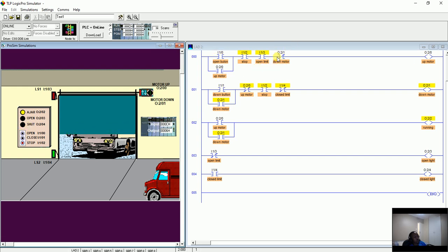The motor down interlock is actually preventing the motor from going the other way around. Imagine if the motor is turning in this direction, and all of a sudden you reverse it without stopping it first, it will burn. So hopefully you understand and you enjoy the practical application for this process.